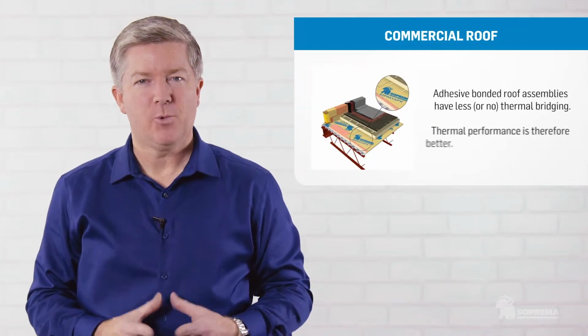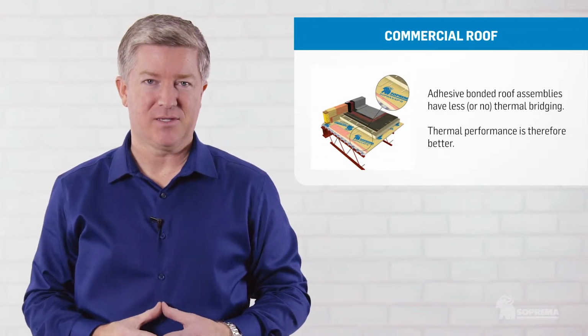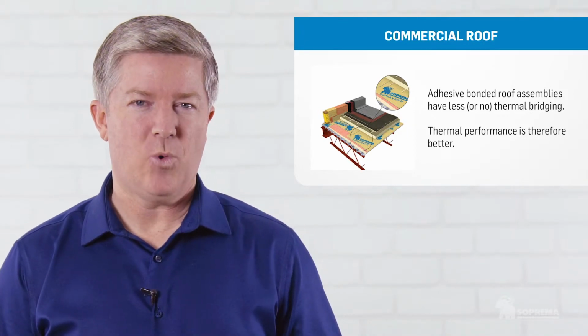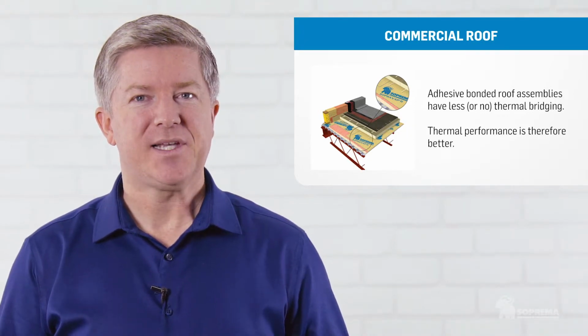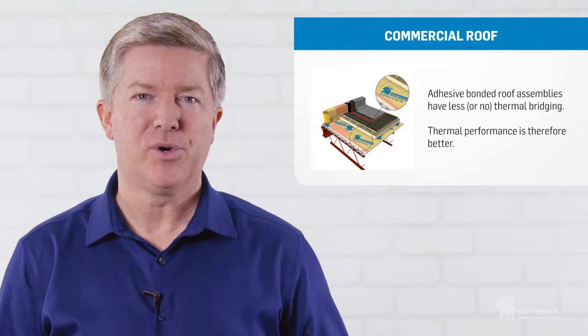In winter, after a light snowfall, a thin layer of snow accumulates on the roof. This is what you might observe when you look at that roof. On this image, at the location of each fastener, there is an important thermal bridge that allows a significant amount of energy to escape the building. What's happening? The snow melts where plates are present throughout the roof. By changing the mechanically fastened system to one using adhesive, we greatly reduce or eliminate thermal bridges. Consequently, a roof assembly where insulation boards are adhered will significantly reduce energy losses due to thermal bridges and increase energy efficiency of the assembly.